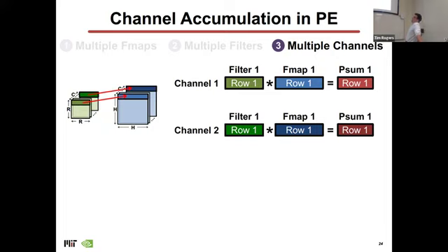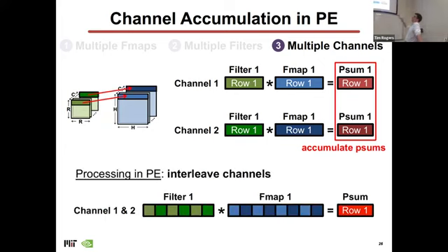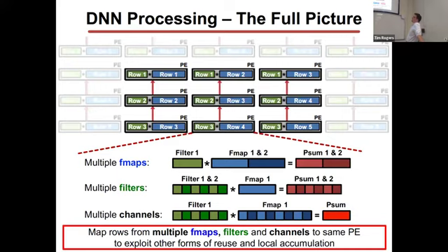And then as I scale channels, which we haven't really talked about, but that was in all of the other diagrams. So now even if I just have 1 filter, I have multiple channels in that filter, I have to have also multiple channels on my activations. So here they're going to be accumulated, right, across the partial products, which means that the rows are going to be accumulated. So I need to basically interleave the channels of my filter and the channels of my input activation to produce that aggregated row. Okay, so you can keep that partial sum happening within the processing element.